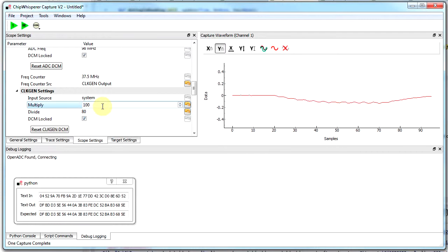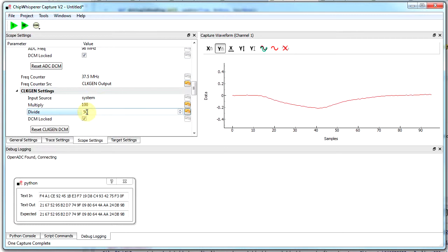It's important to note that on this board with the Virtex 5, there's no decoupling capacitors because they were removed for side channel. And we'll also need to make sure we have the voltage for the internal part of the FPGA set correctly. And it's some of these things I'm going to show you that affect our result. So I'm going to increase the frequency to 37 megahertz. Let's go all the way up.